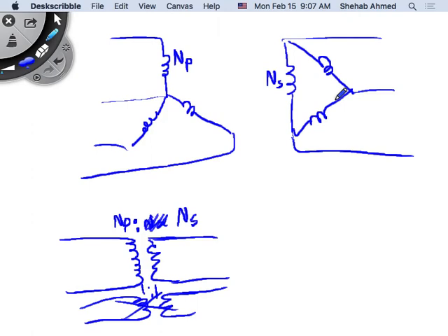But how do I deal with this? I have to figure out what the voltage is on the corresponding single phase load. I will create an imaginary single phase star connected load here, and then the voltage that I see on one of these phases, on phase A, is what I will have here, right? And that voltage is what?